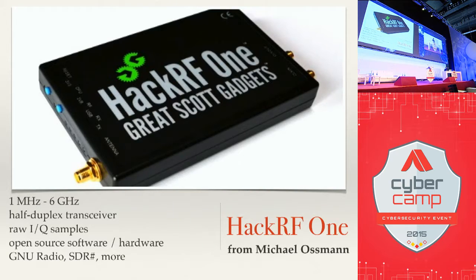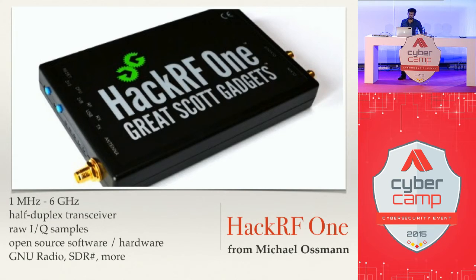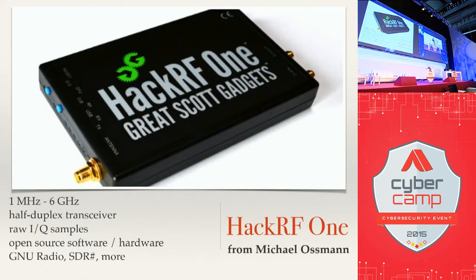So let's start talking about the devices that I'll actually use to reverse engineer something like this. I like to use HackRF1. It's a transceiver. It can receive and transmit. It has a very wide operating range, so from 1 megahertz to 6 gigahertz.